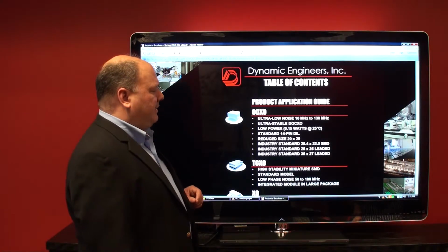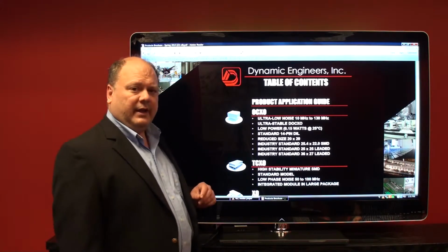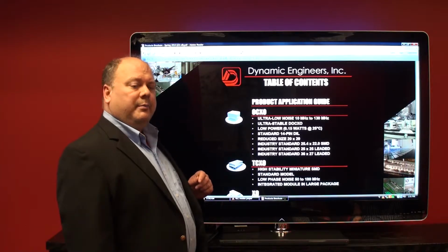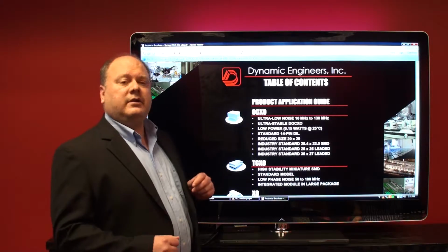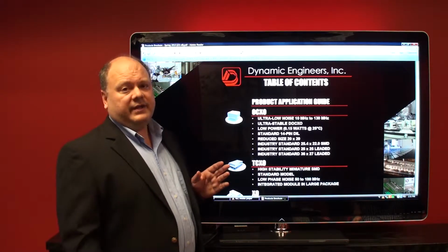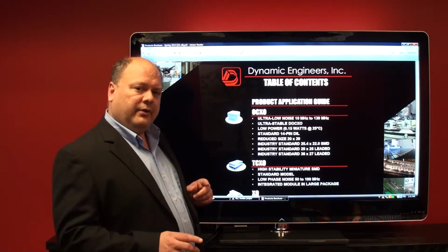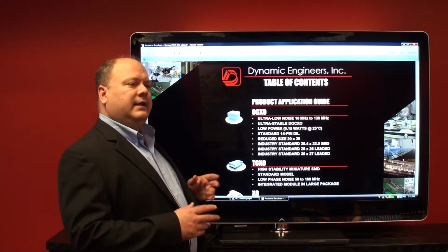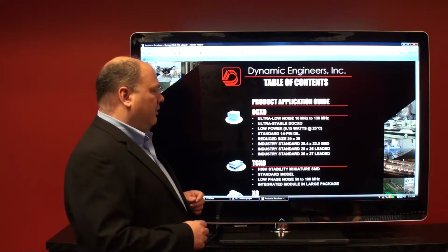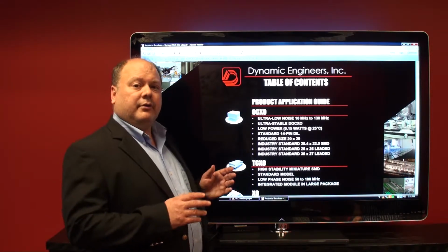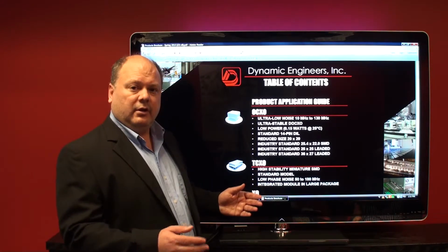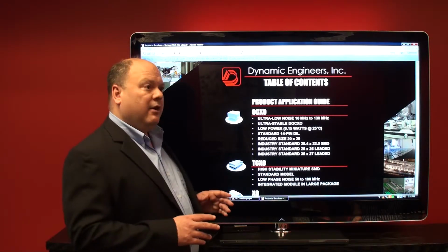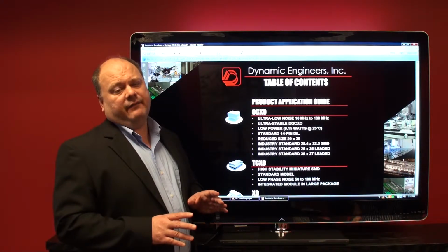And let me explain something about general models. Anytime you go to the website, it will show you, for an industry standard 25 by 22 millimeter, for example, OCXO 13, let's say 1322. Any OCXOs, or TCXOs, or any other oscillators that have 13 with 2 other digits is a general model. It's not a custom specification. What I mean by that is it gives you a general idea of the performance range in that particular oscillator package. For example, a general frequency range might be, say, 2 megahertz to 80 megahertz, or 8 megahertz to 100 megahertz. The point is, it's a general model, and for your specific customers, they are going to help you decide what specifically they need from that general model.